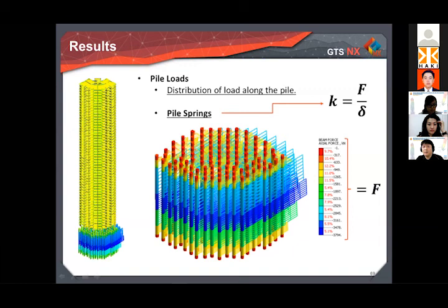The reason for this is mainly because of the positions of the piles inside the raft, which can be affected by the load location of the column. Also due to pile group effects, which tend to decrease the deformation of the piles, meaning that some may not offer the same reaction as others. So the generated springs for each pile may be sent to the structure team or simply exported back to Midas Gen, as I mentioned previously. And the very same thing can be done for area springs.